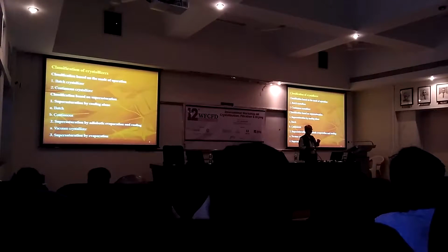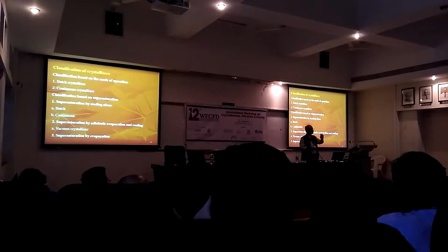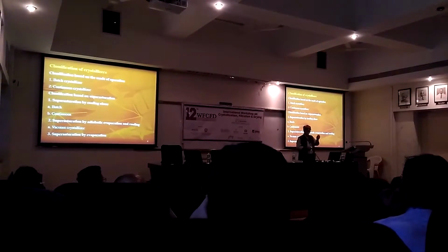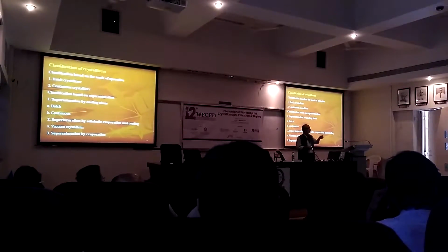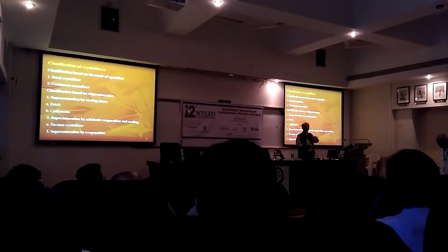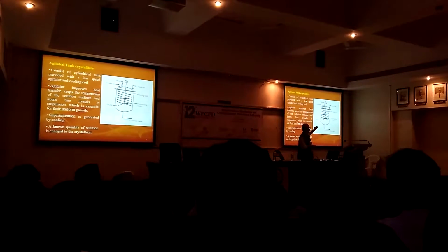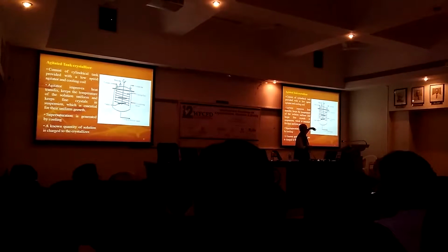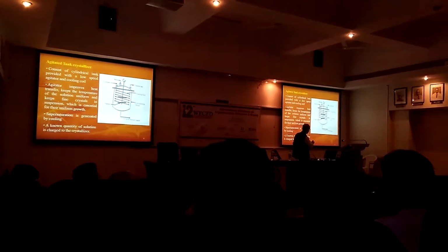As discussed in the morning in the first lecture, essentially you need to create a supersaturation and then allow that supersaturation to get desupersaturated in the form of deposition of the solute molecules on either already existing crystals, which are in the form of nuclei, or added seeds, which are going to provide the phase for the deposition of the solute. So this is a typical agitated crystallizer, and you can imagine this is the standard crystallizer which is operated in most crystallizer operations.